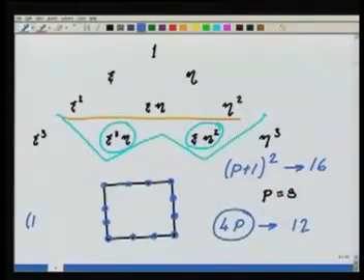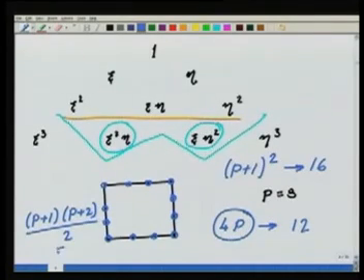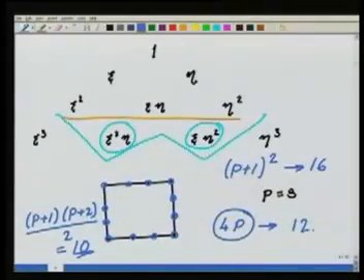If I had taken triangular elements, then I would have (p plus 1) into (p plus 2) divided by 2, which would be 10 terms. So if I had used triangular elements of order 3, I would get 10 functions to solve for, 10 unknown coefficients in each element. If I use tensor product of order 3, that is bicubic, I would need 16. If I use the serendipity of order 3, I will need 12. So depending on what cost you want to pay, one can use one type of functions or the other.